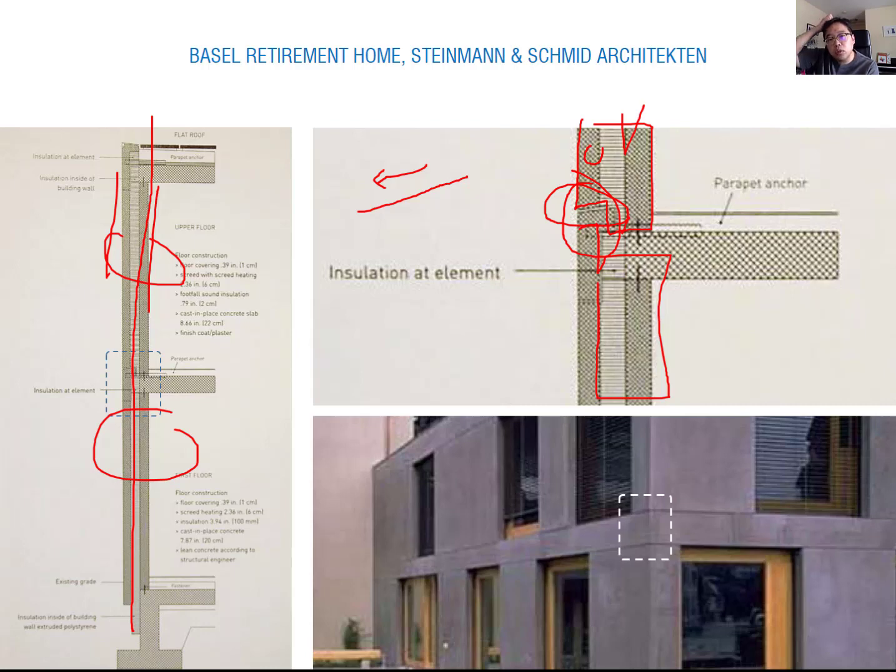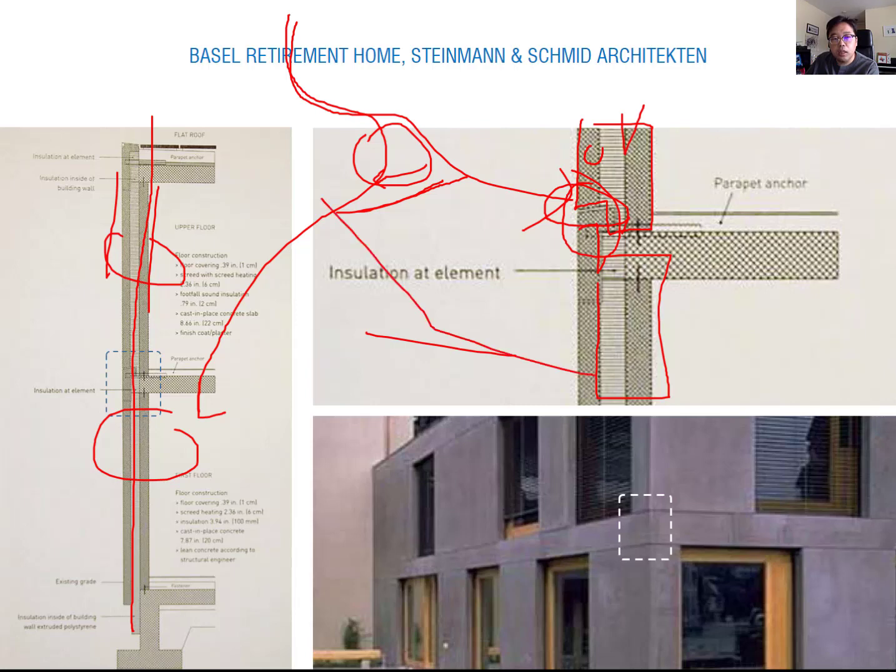You remember the joint has a lot of moisture transfer and water transfer through it. So they make a 2% slope to let the water get out as much as possible. When you make a slope, it is hard for water to get into the insulation layer, but when it is flat, it's much easier to get in. So they intentionally design the slope between the joints.